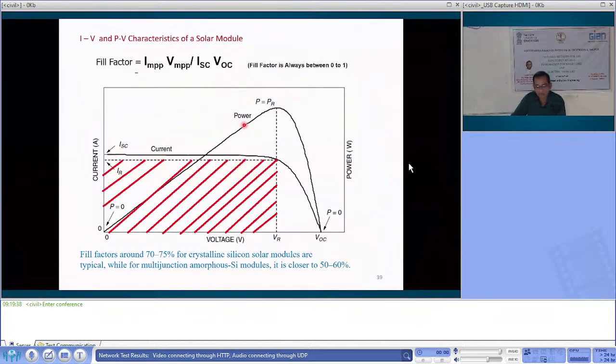Now when you plot IV, PV characteristics, they are shown here. Now the top of the PV curve, that maximum power, also called rated power here, or PM, you take projection on the bottom curve. Where it intersects the IV curve, there, okay, you mark that and take projection on the x-axis.